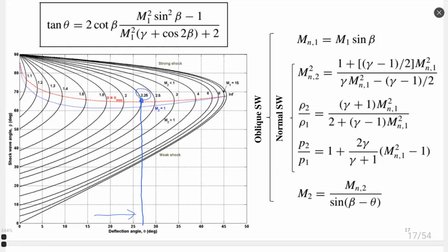For example, we work with Mach 1.4. It means that we can have a maximum of 9 degrees of the body to obtain an oblique shockwave. It's better to work at smaller values, so we will have this intersection, right? If we already have, for example, 15 degrees and Mach 1.4, intersection will not happen. So in this region, we will definitely know that a normal shockwave is happening.